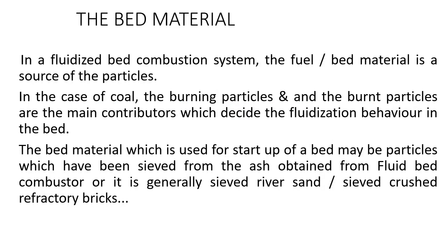Now, the bed material. In a fluidized bed combustion system, the fuel bed material is the source of particles. In the case of coal, the burning particles and the burnt particles are the main contributors which decide the fluidization behavior in the bed. The bed material which is used for startup of a bed may be particles which have been sieved from the ash obtained from a fluid bed combustor, or it is generally sieved river sand or sieved crushed refractory bricks.